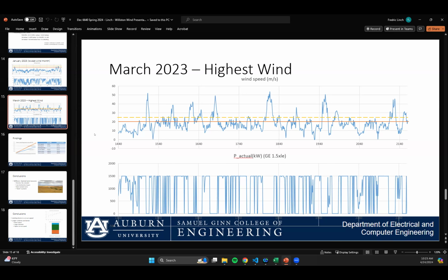And this is just an area that's always coming up because those lines are always close to their limit, because of all that transmission, all that generation that's coming up into that load pocket. And then on the planning side, there are handfuls of people trying to connect, but the limiting factor is whether the transmission grid can handle it. People want to provide the generation, but the limiting factor is the transmission. And so the closer that you can build to the load center, the better.